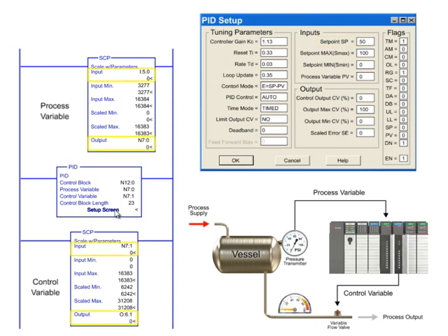As the PID instruction is executed, a scaled error is generated by subtracting the process variable from the set point. By increasing the control output, the error is reduced to attain the set point as the PSI is raised in the system. In other words, the valve position is gradually closed to reduce the pressure loss. Upon reaching the set point in the system, the control output and scaled error is reduced to 0.